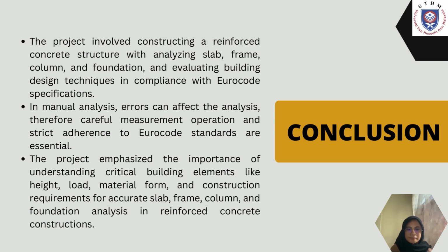the structural stability, strength and flexibility. The project applied reinforced concrete design concepts to the architecture of a 4-story building, focusing on the critical roles of building elements like height, load, material form, number of bars, column and beam size, and also the construction requirements. Careful measurements, operation and strict adherence to Eurocode standards were essential in the project. In summary, the project yielded a thorough comprehension of slab, frame, column and foundation analysis in reinforced concrete constructions.